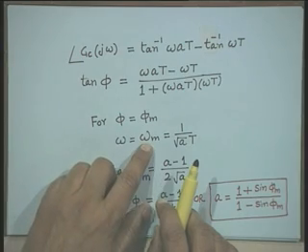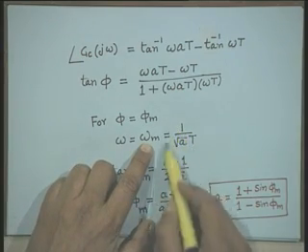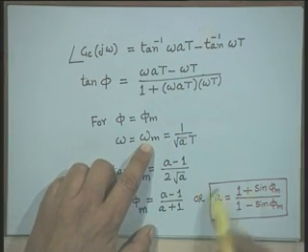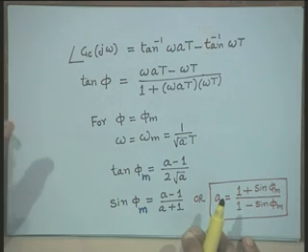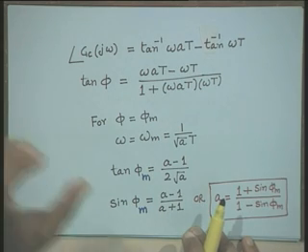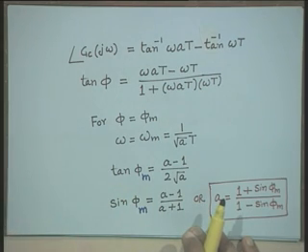So, using this expression and this equation, I know both things: how much phase shift or phase lead this phase compensator is to provide, and at what frequency it is to provide it.